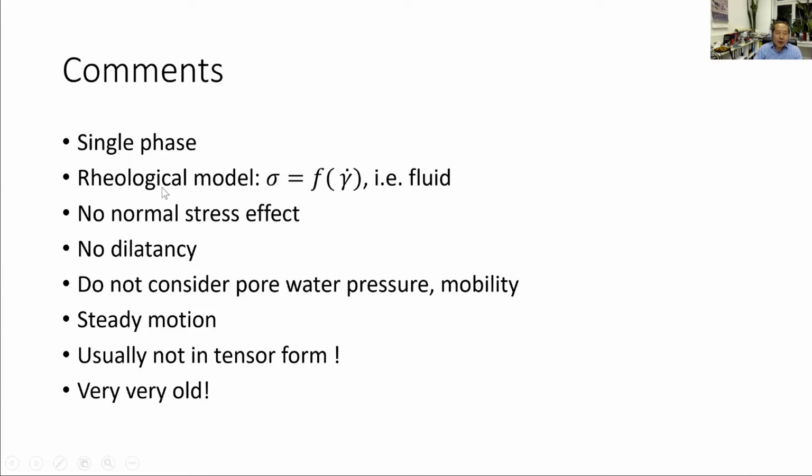And they make use of the constitutive model, usually the so-called rheological model, expressing the stress as a function of the strain rate, right? And that is a fluid. And we say granular material is certainly not a fluid. Why? We know that such material during the flow will exhibit some kind of normal stress effects. So what is it? Normal stress effect is something very unusual in fluids, but it's very common in soil mechanics. This means when you imagine you have a shearing in one direction, you may develop a kind of normal stress perpendicular to it, right?